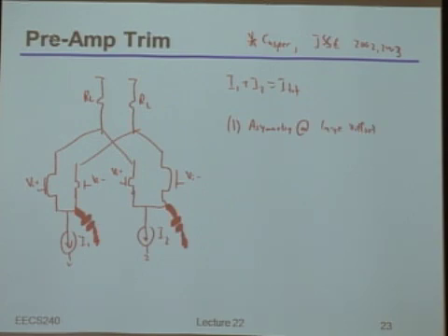It turns out, by the way, that it's not only that you have asymmetry, it's actually even the fundamental thermal and flicker noise of this thing that will vary as you change those offsets. That's an exercise I'll leave you to do at home. But there is one more, perhaps not negative, but limitation in this thing. So what do you think sets how big of an offset you can actually create in this thing in the first place? Like, what sets the range?